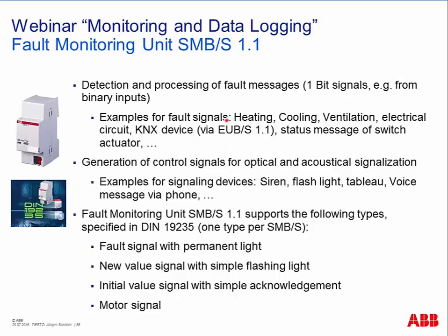So it could be only a telegram from the monitoring unit. So not only binary inputs, but also any telegrams can be integrated in such a fault management. Or you take a status message from a switch actuator, any important load behind. Think about our switch actuators with current detection. So you have really the feedback, is a load properly working, yes or no? Can be integrated as well.